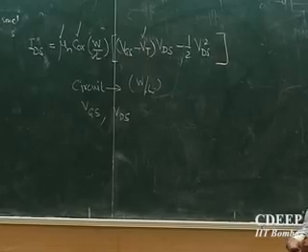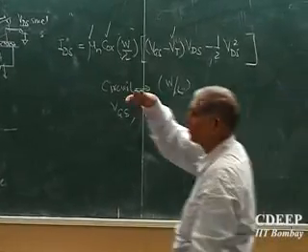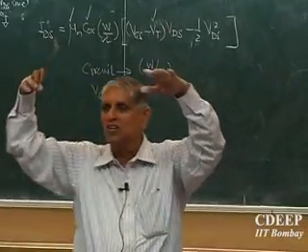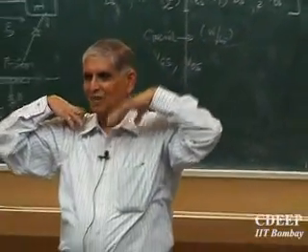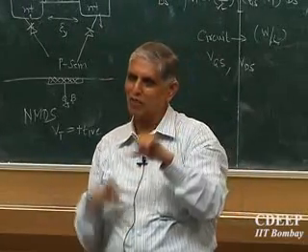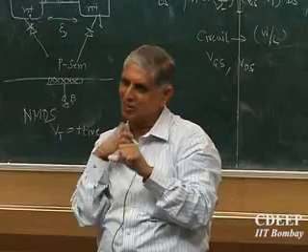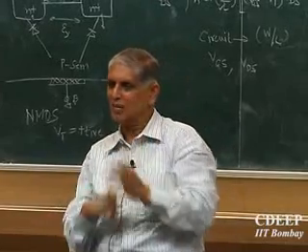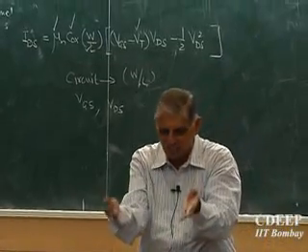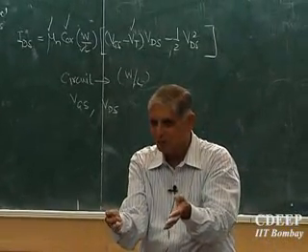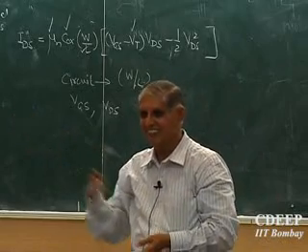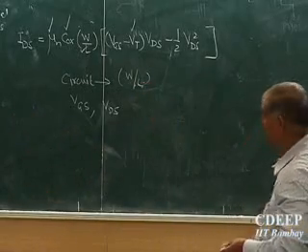So what does design mean? That's what I said the other day. Design is always on the plan. On the top surface, whatever W's I use, that's my design. Whatever I do in the cross section down, that's the technology. I fix L, I fix VT, I fix everything, mobility, everything by technology. So designers have a tough job because they say this is the technology, but the performance wanted is this. How do I design? That's what all the tricks of the trade in circuits are.